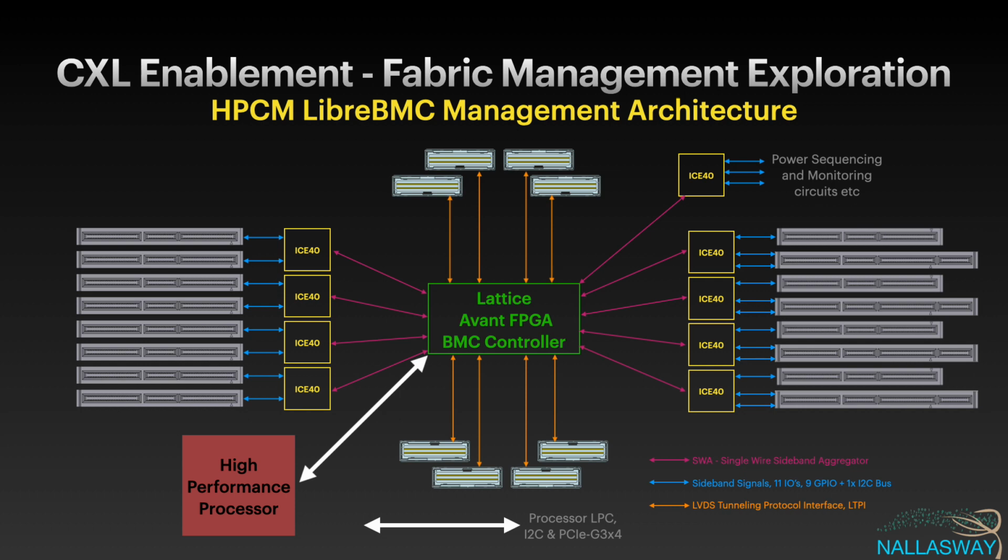And so there is an activity that's been going on for a number of years called LibreBMC, where they're actually using basically blank canvas FPGAs, and Lattice and Xilinx are the two participants in this effort to actually make the BMC controller, and then you layer in soft processors or low-level hardware management, and that's all open sourced as well inside the FPGA.